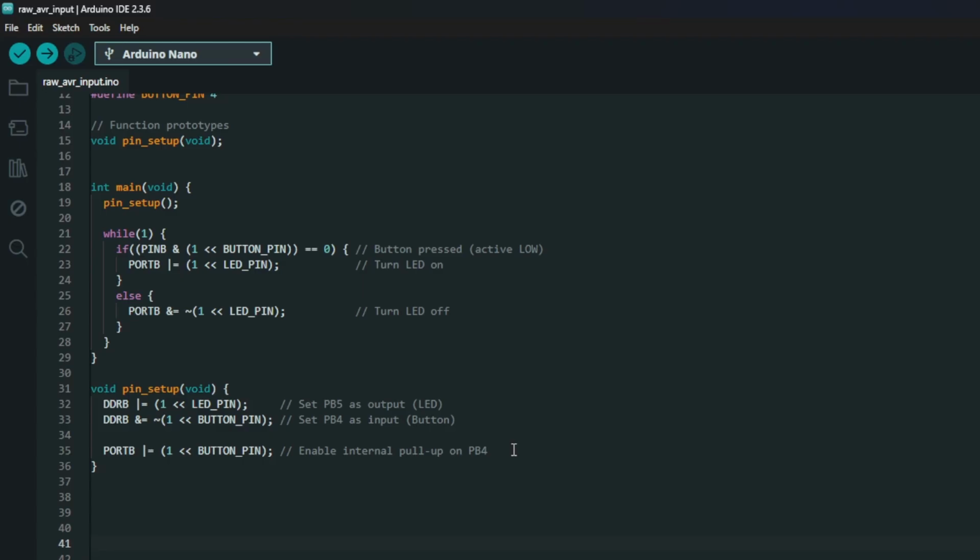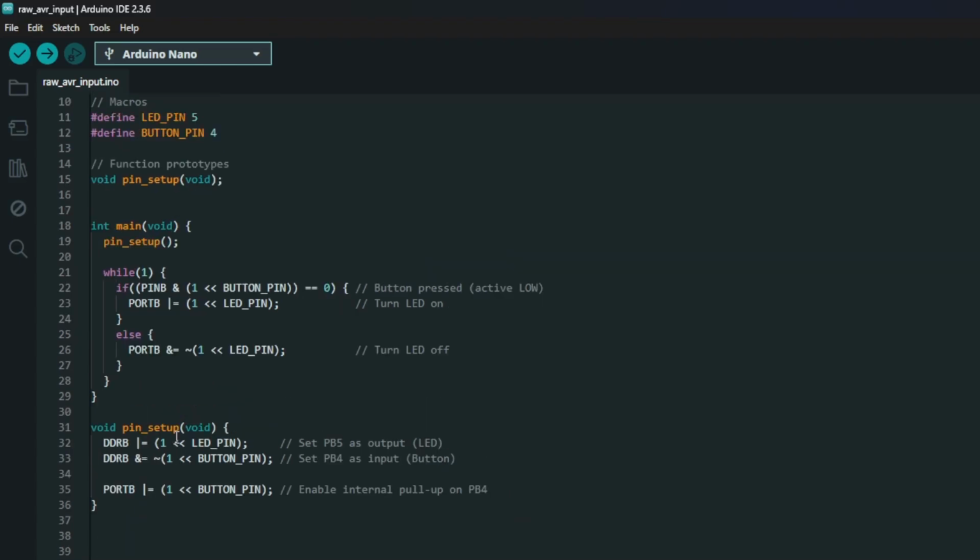So instead of being unpredictable, we can make this pin predictable using 5 volts and a resistor. This resistor is a very high value so that we don't drive a lot of current inside this pin. And again, these are all details. Unfortunately, I will not discuss them here. Just consider that we have to use a pull-up resistor on port B4. And this is essentially what this function does. Now,